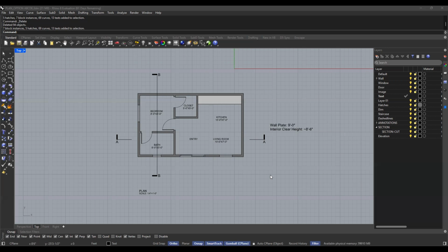No furniture is needed in this assignment or in this tutorial for section and elevation. So turn on layers like walls, doors, windows, and create one layer. I'm going to work with section, so I have already created one layer and I called it section, right? Then feel free to create sub layers for this section, so you can just add more sub layers for your section layer.